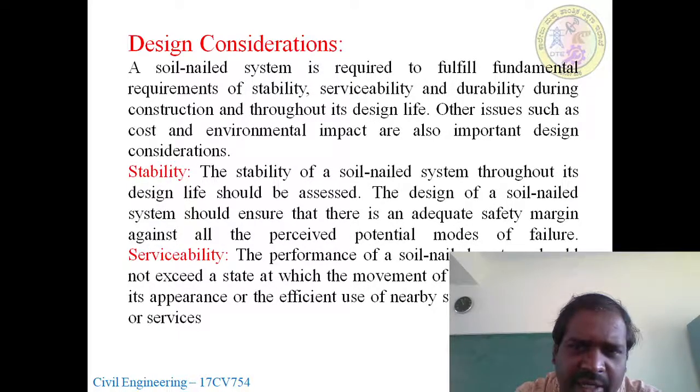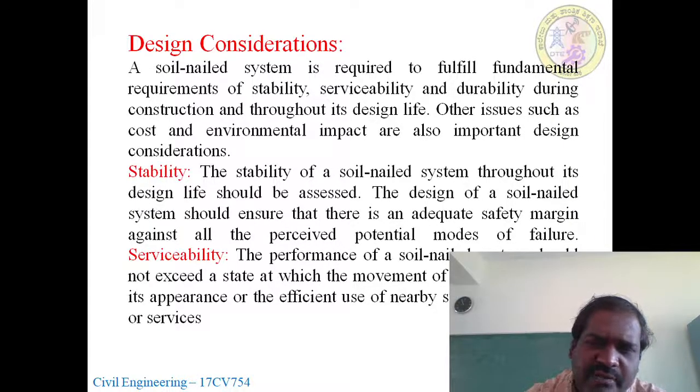So here we have studied the stability. The stability of the soil nail system throughout its design life should be assessed. The design of a soil nail system should ensure that there is an adequate safety margin against all the perceived potential modes of failure. The next, serviceability. These come under the limit state method. The codes that will be used are the Indian Standard codes. The performance of a soil nail system should not exceed a state at which the movement of the system affects its appearance or the efficient use of nearby structures, facilities or services.